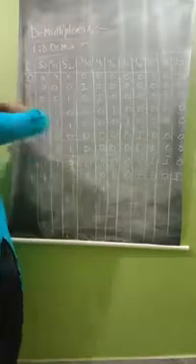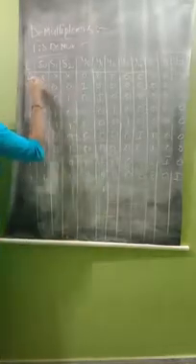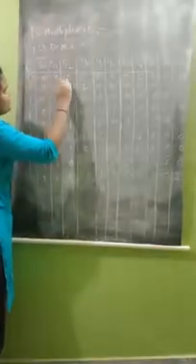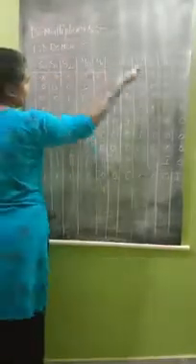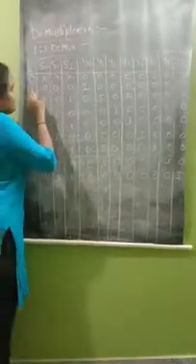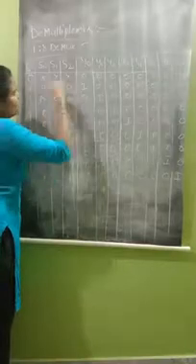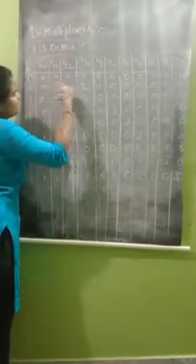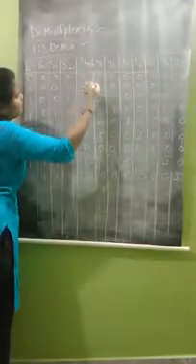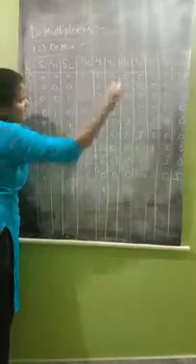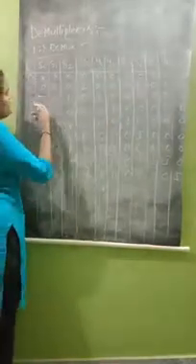Okay, so once again I explain. Enable 0, then S0, S1, S2 do not matter, and the output is completely all 0. Next the enable is 1, then the selecting lines 0 0 0. So it takes 0 0 0, then Y0 is enabled, and the remaining are 0.